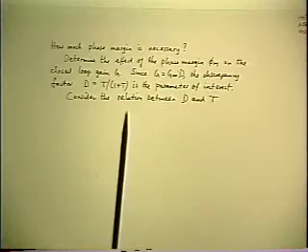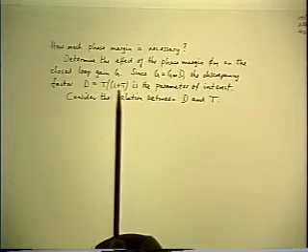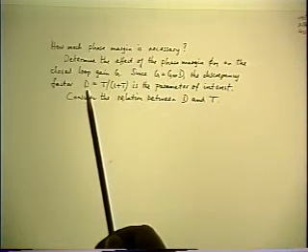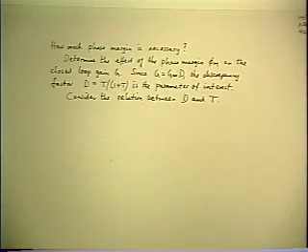Now that part of the answer you can't give in general, because it depends on the sensitivity of the phase margin to the component tolerances, and there's nothing you can say about that in general without going to the specific design. But it's certainly an important thing that you have to bear in mind, and we'll see an example of that. So there's not much we can say about it other than to recognize you have to take that into account. So let's go back to the first part of the answer, which you can answer in general, because of a unique relationship between phase margin and discrepancy factor. Since it's unique, we can say something about it in the general case. So let's start working on that.